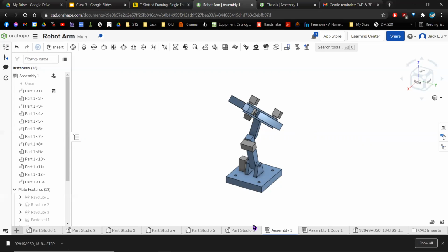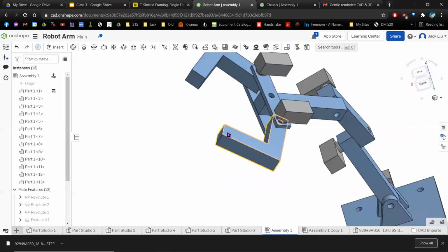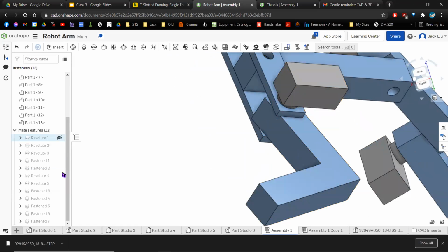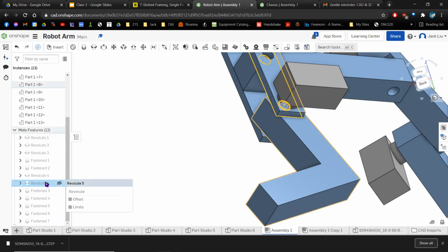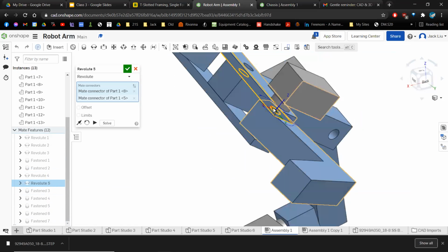I just created the two closing ones, but it won't move. So do I just put Revolute mates for that? Yeah, so you can put Revolute mates. These fingers are connected right here. And if I look at the list of mates, yeah, this is a Revolute mate that was added. So let me open that up. You can see it's connected to the top in the finger.